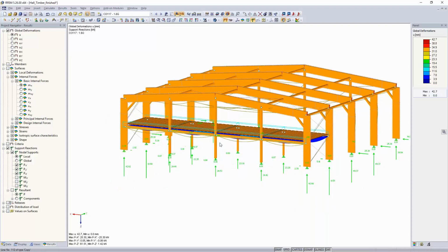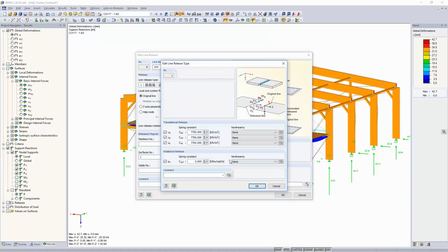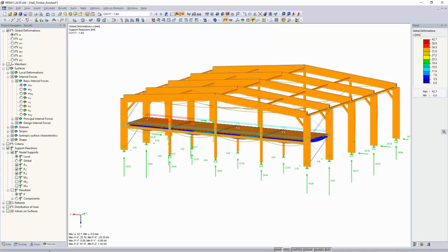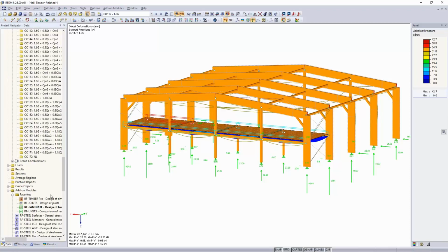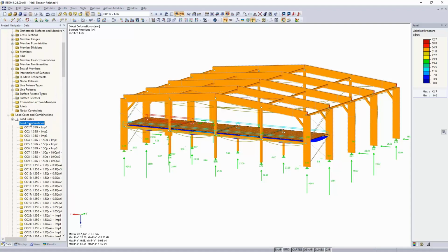But what he did not do, and what makes absolute sense when you model the structure, was to also generate the stiffness for the line hinges and the releases. So he just generally introduced this stiffness here, but for the ultimate limit state you have to reduce this by a factor of 2 divided by 3, the slip modulus. For everybody who wants to know where it is written, it's in equation 2.1 in the Eurocode 5, and you can do it similar to what I did before with the serviceability limit state.